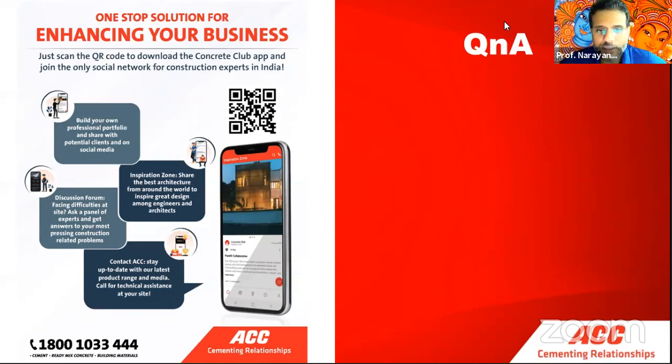Is it possible to design UHPC using GGBS waste or fly ash as binder in place of cement? You cannot replace cement entirely, because then Manikandan would not do this talk. You cannot replace cement entirely. You still need cement. You need about 50% of cement at least, because the early strength comes from cement. Fly ash and GGBS are wonderful.